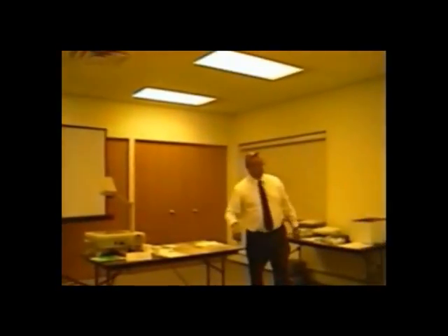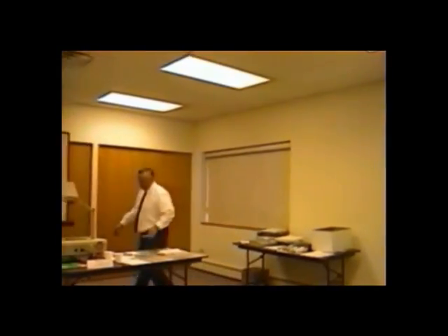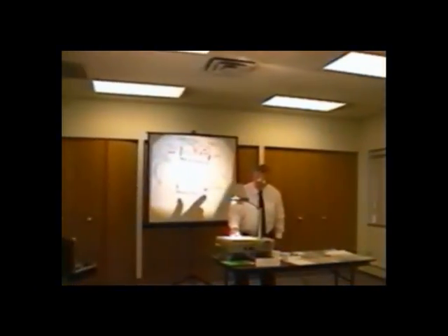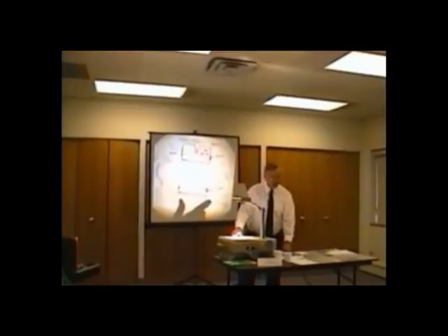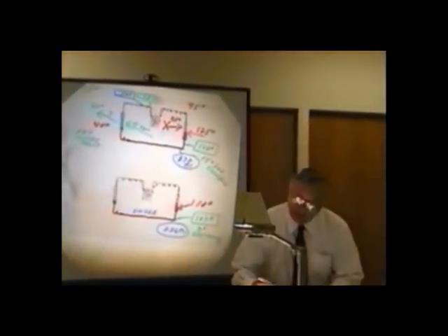Okay? Let's stop and talk again. Normal is 12 to 15 degrees of subcooling. See? Normal is 12 to 15. So right away you say 3. Well, holy cow, there's not enough refrigerant in there. That's your biggest clue. Okay? Now, if my subcooling went down because of an undercharge, watch what happens with the evaporator.